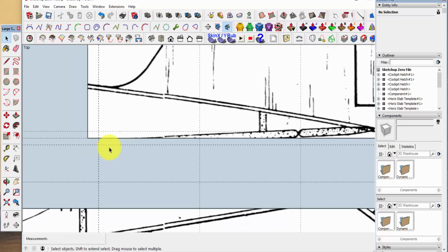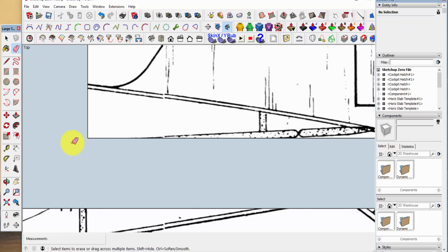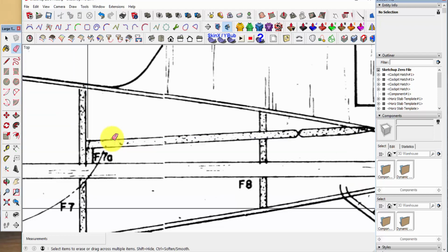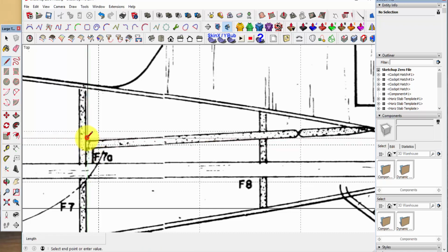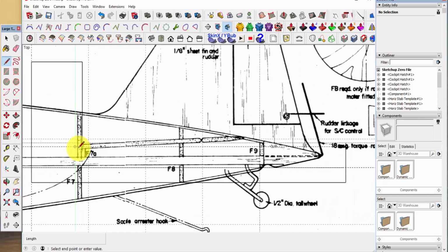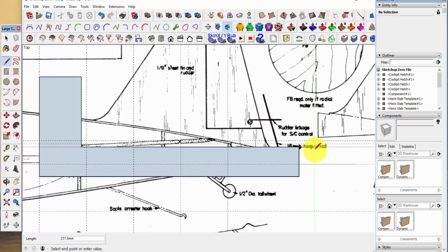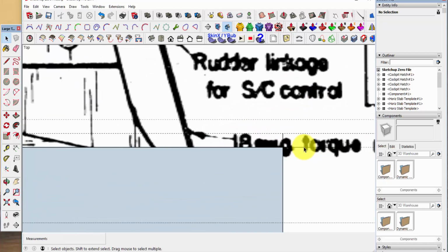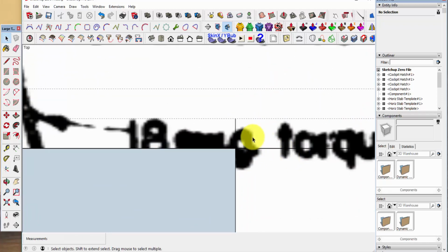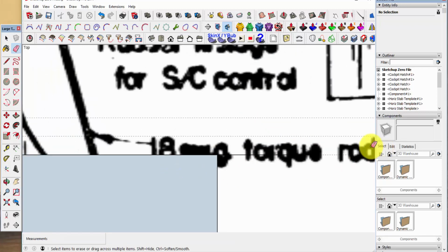So that is going to represent, we erase this line now. And again, if I just erase this line, I would erase this guideline. So now I'm going to use X to get rid of those just temporarily. I'll get rid of that, and now I'll put them back. So we want our baseline now to come down that extra 3 millimeters and out the back on the red axis. Now if we come over here and take a look, we'll see we've got lines just kind of hanging off. That doesn't matter. I'm going to erase them. So I'll erase that. Again, if I erase this, I'll erase my guideline here, and I don't want to do that.